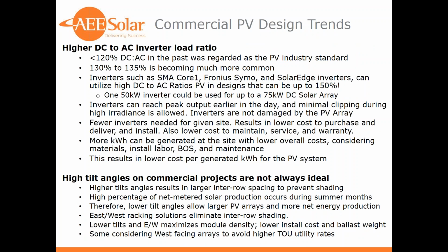So with commercial PV design trends, with the inverters, in the past, most companies had agreed that most installers would try to achieve a pretty tight DC to AC ratio and not have a lot of extra PV, concerned about power clipping and wasted power.